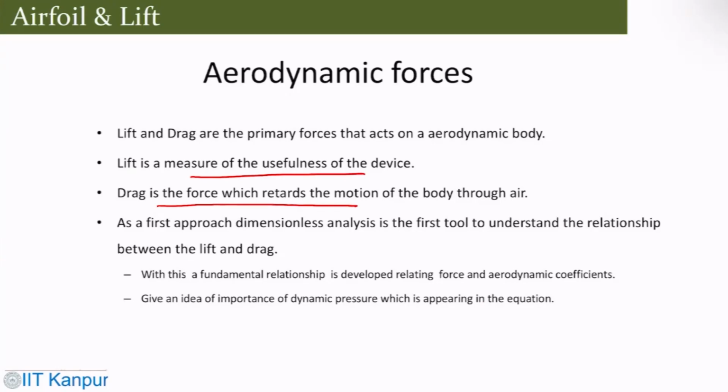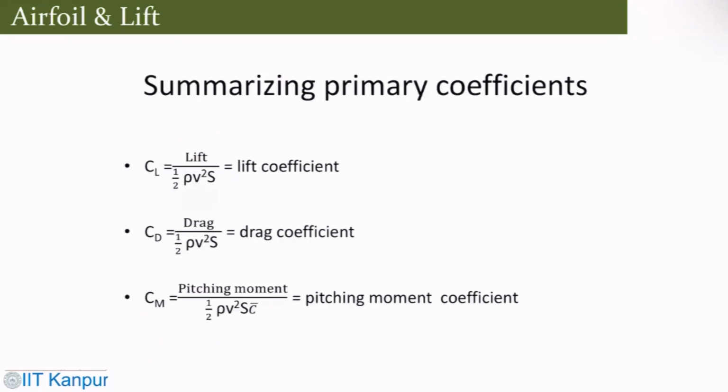So one has to understand the relationship between lift and drag, and a fundamental relationship is developed relating force and aerodynamic coefficients. If you look at those, you have the lift coefficient, which is the lift force divided by area times dynamic head, the drag coefficient, and the pitching moment coefficient. These are the fundamental aerodynamic coefficients one needs for design and things like that.